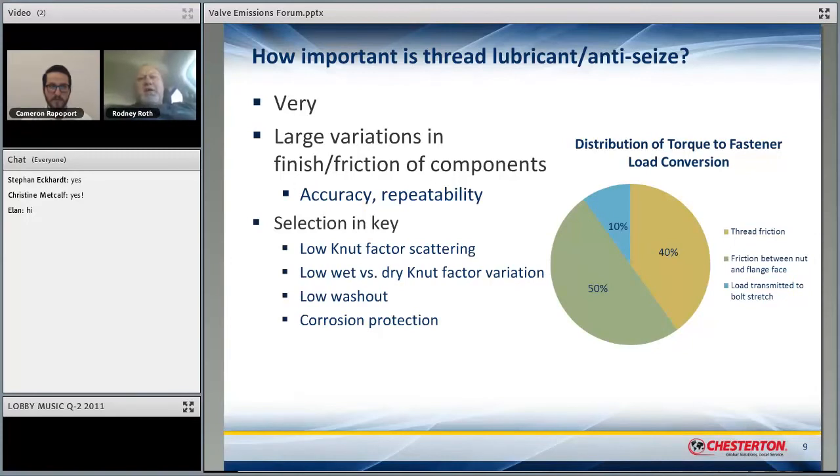And so if you do not have an anti-seize that has a close spread between a wet friction factor and a dry friction factor, then no one knows how to torque those valves effectively. And so we found that the use of 783 ACR, which is our ceramic-based product, exclusively to those bolts that would be considered carbon steel, or the terminology is ferritic, has a very narrow spread between wet and dry. And so the loading is very similar from day 1 to day 1,000.